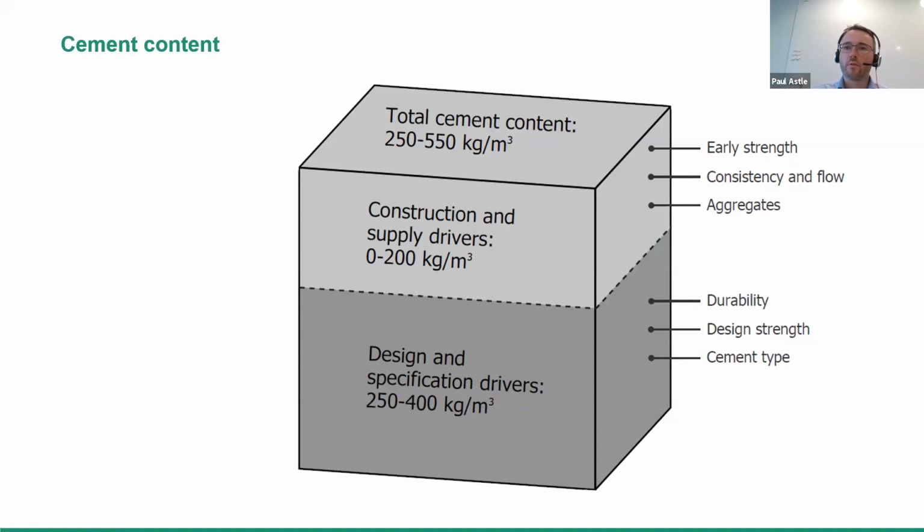And in terms of what influences that content, this is my assessment, so don't take this as definite, but I would suggest that perhaps 60-70% of it is down to designers, so things like durability, design strength, cement type. Of course, that also plays a role in cement content. And then the other part of it is down to construction and supply drivers.